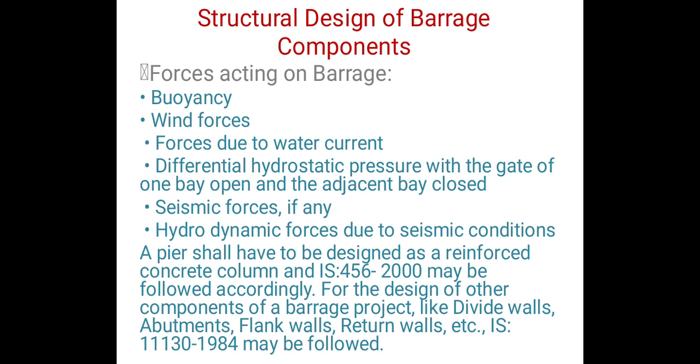A pier shall have to be designed as a reinforced concrete column, and IS 456-2000 may be followed accordingly. For the design of other components of a barrage project like divide walls, abutments, flank walls, return walls, etc., IS 11130-1984 may be followed.